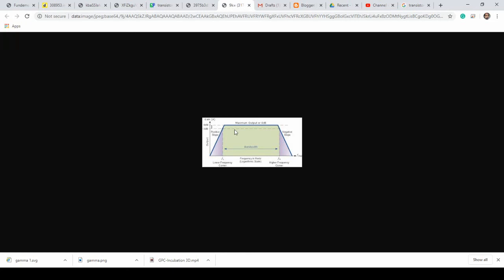I could have a transmitter that's working on a particular band, and if I have to change the frequency and the transistor does not support or give me high gains in that particular frequency, my efficiency won't be that great. So understanding frequency and identifying at what frequency to what frequency the gain is moderate or above the desirable value, that is a frequency band I need to consider as my bandwidth. So the word bandwidth would be coming up very often.